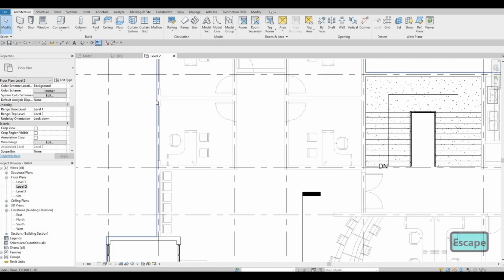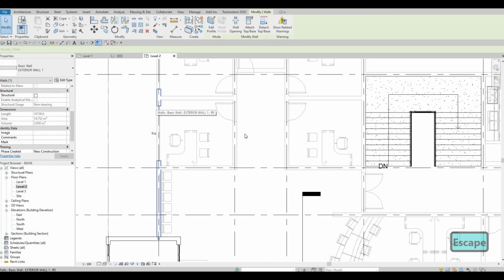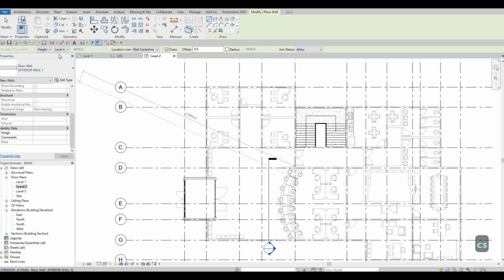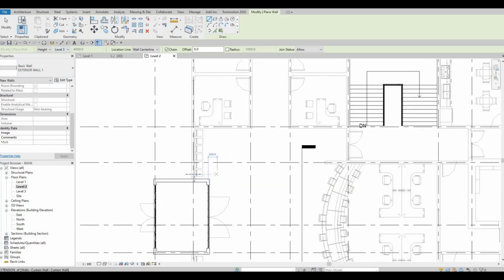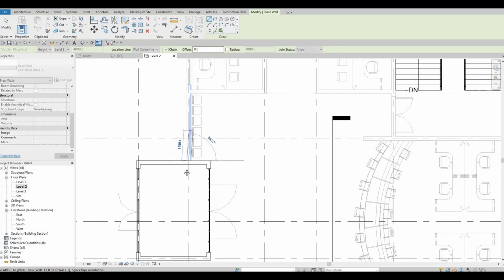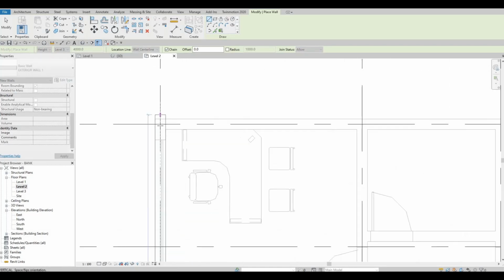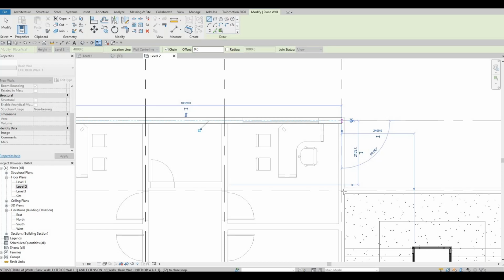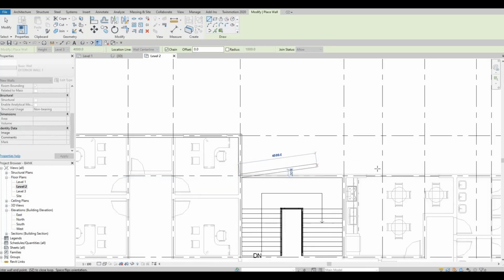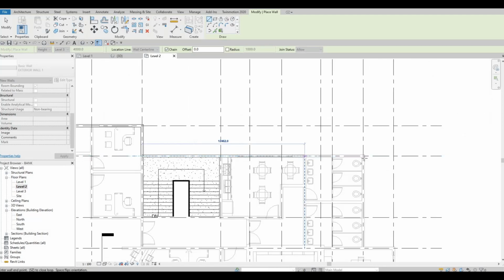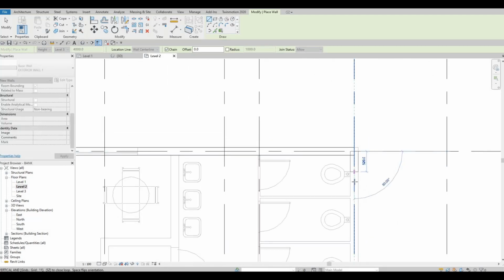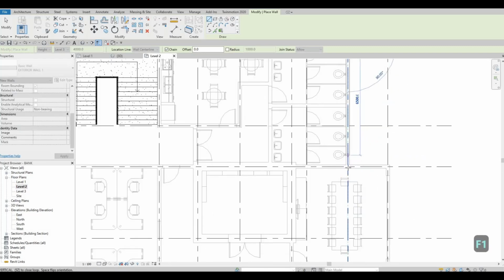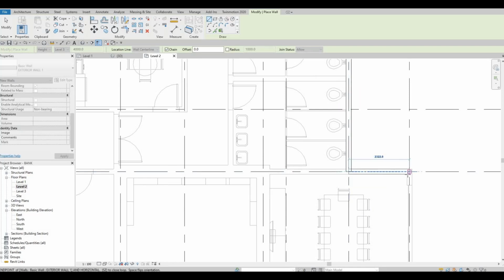select here. So now I'm gonna select this exterior wall number 2 and then CS on that, and here it will be automatic, it will be on level 2. So now we just need to go around and copy what we have below. It will be confusing if you think about it, but at the moment it's better than going back and forth to see where it is. So this is the best way of basically tracing anything that you want to do. So here I'm just tracing all the exterior line.